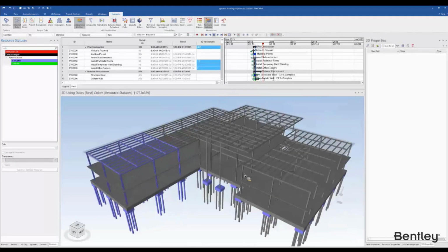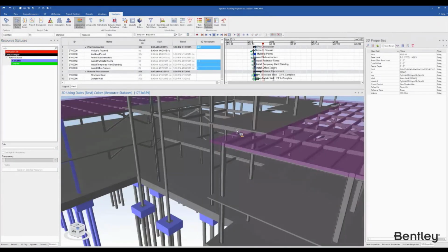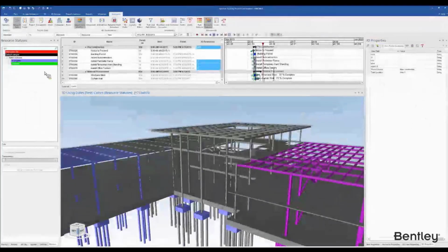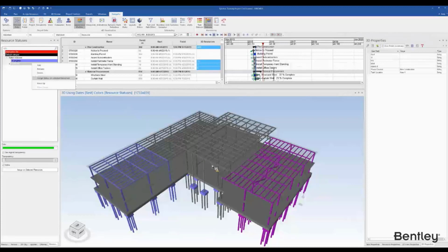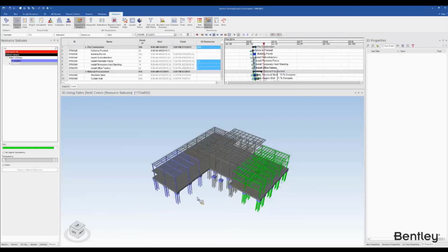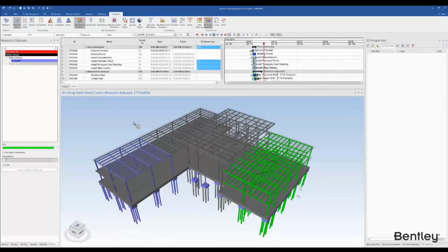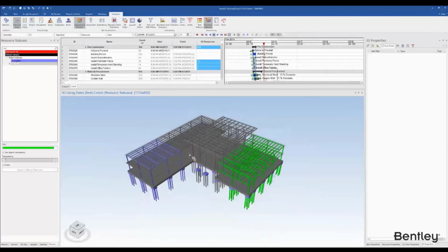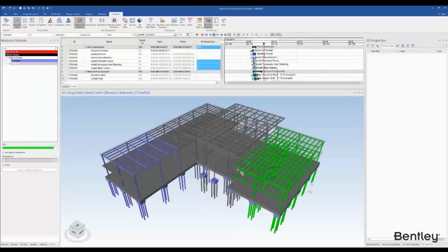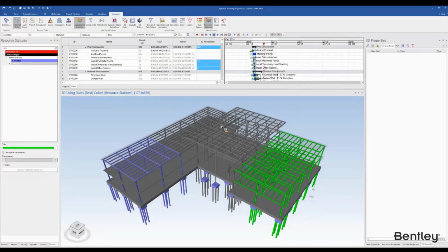If I select this one and say, okay, these elements are complete. You can use your focus time to see at what stage those elements were statused. This does not show the appearance profile at all. All the elements which have not been statused are showing dark gray, and the ones which have a status have a color.